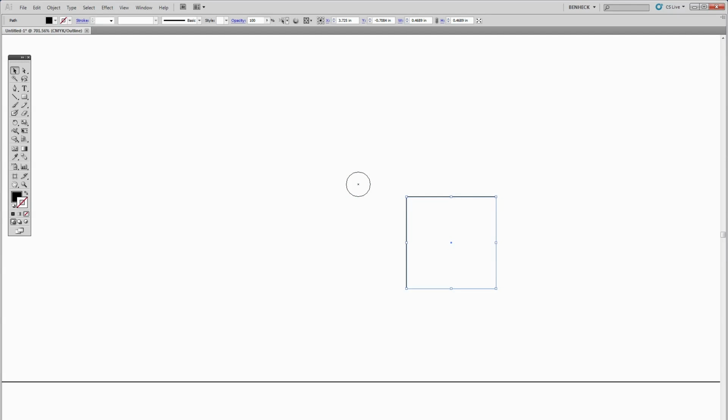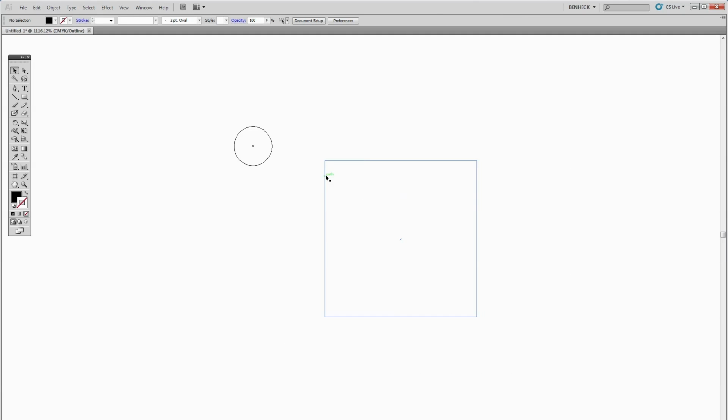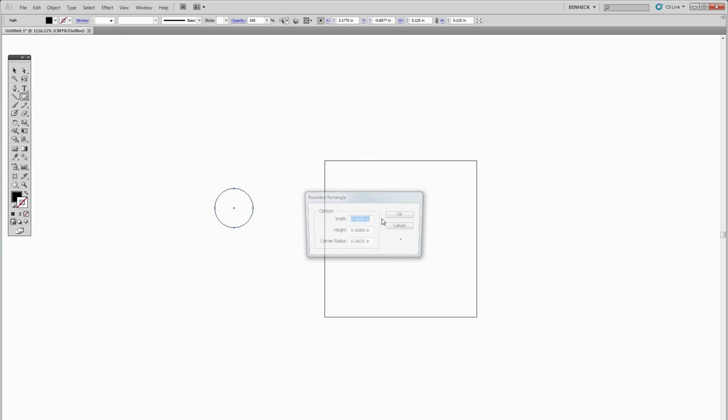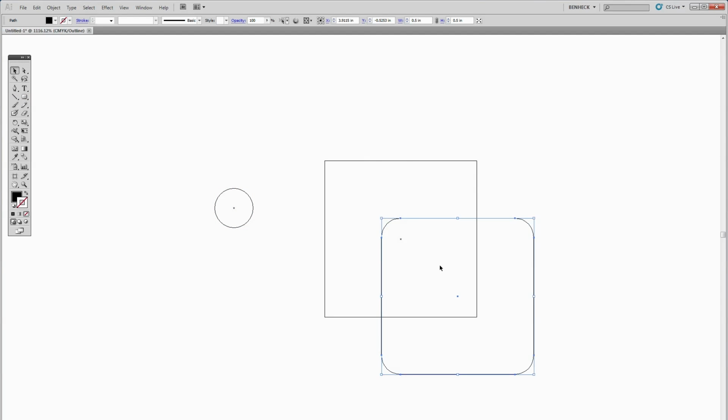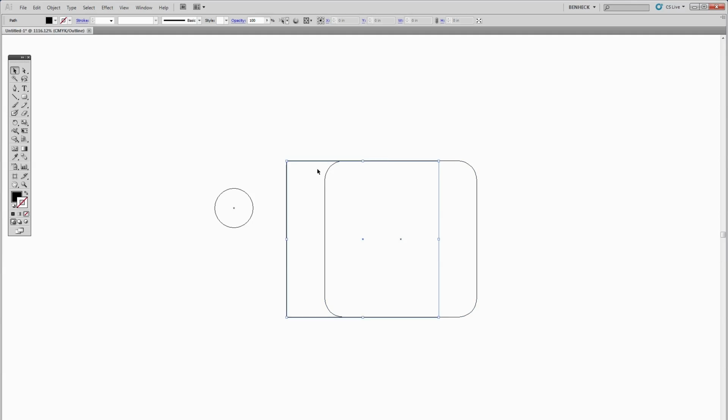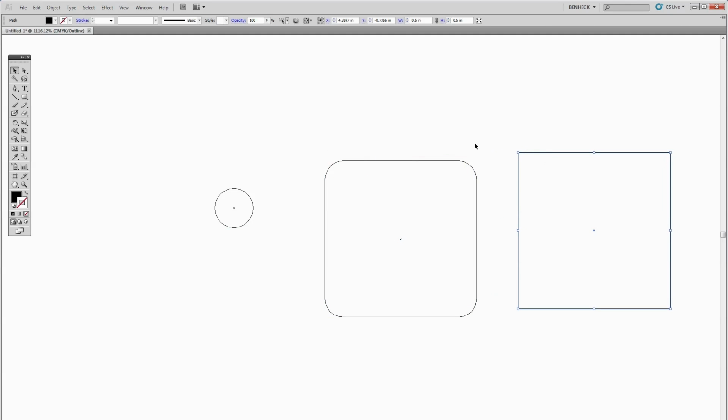Let's say you had a square that was 1/2 inch. Now, if you were pocketing this or cutting it out with the bit on the inside, you wouldn't get a square shape because the bit is round, see? The resulting cut would look like this. You'd have rounded corners, and maybe that's what you want, who knows? But it might not be, especially if you want to make something slot into it. It wouldn't work, because if you tried to slot a square object into an object with rounded corners, well, like that one song, a circle won't fit where a square should be. Wow, I just quoted, who sang that?